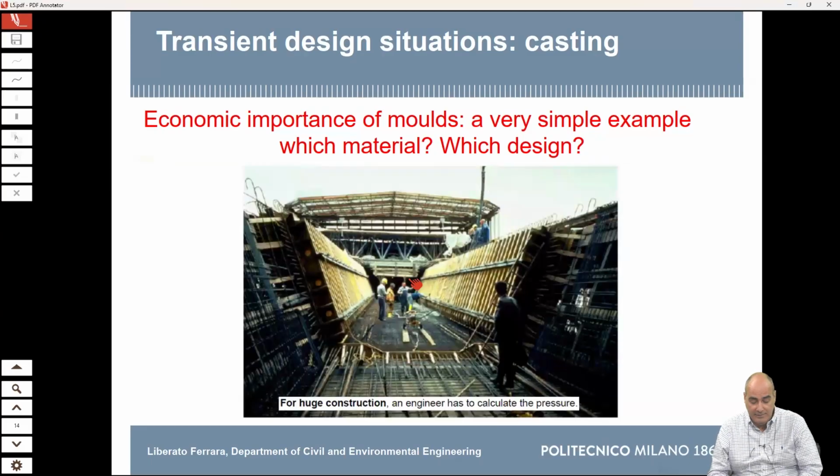Well, here you have a caisson beam for a bridge. You see that it's not uncommon that if you have a 30-meter span bridge, the span to depth ratio is 15. A 30-meter span means a 2-meter deep beam. So people can stay inside. And this brings another important point. Imagine, as we were saying yesterday, that you have to cast concrete vertically for 2 meters.